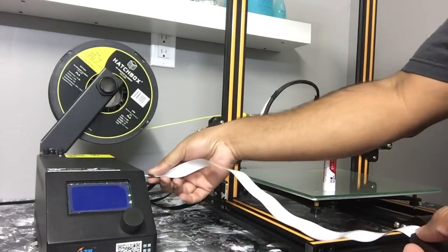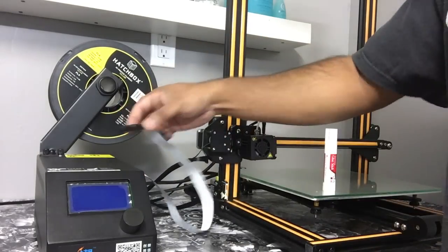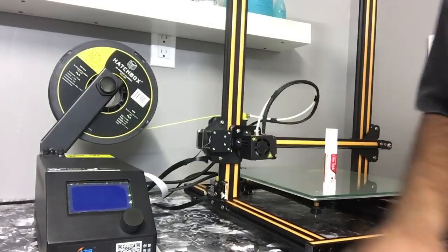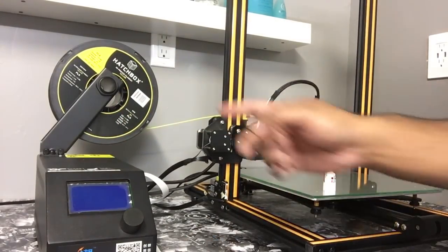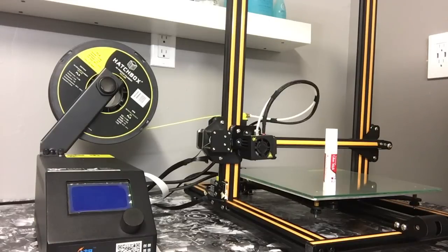So I take it, put it on the side of my control box, and usually I just lay this down next to it. I'm eventually going to tape it up here, but then you just insert your micro SD card and you're good to go, and it'll start reading it. So that would be my best solution, because now you're not ever going to mess with that unless you have to. Okay, so just keep that in mind. Buy a micro SD card extension cable. It works very, very well.